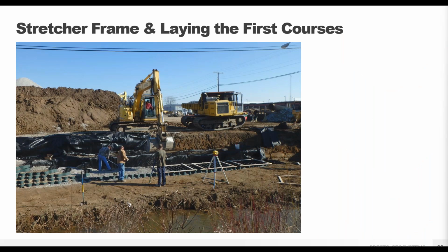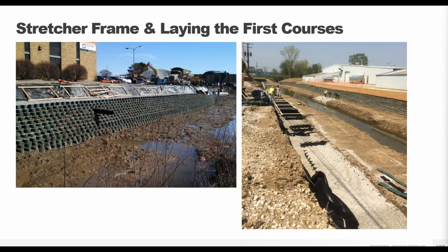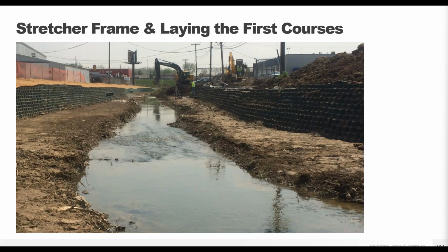And the process repeats, going down the line, connecting panels side to side, and working in parallel for an efficient installation. As one side of the stack channel was completed, onto the other, also using stretcher frames. And here we see the newly constructed GeoWeb walls on either side of the watercourse.